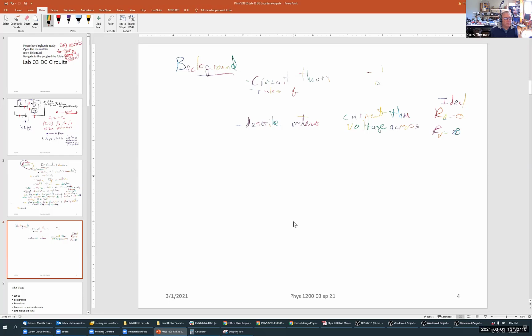What else? Oh, right. And this is where you'll see, and that has to do with why we saw those discrepancies. I'll remind you that our analog voltmeter is generally about 10K, and our digital voltmeter is generally about 10 megaohms. But save this for later when you're analyzing the part one data.